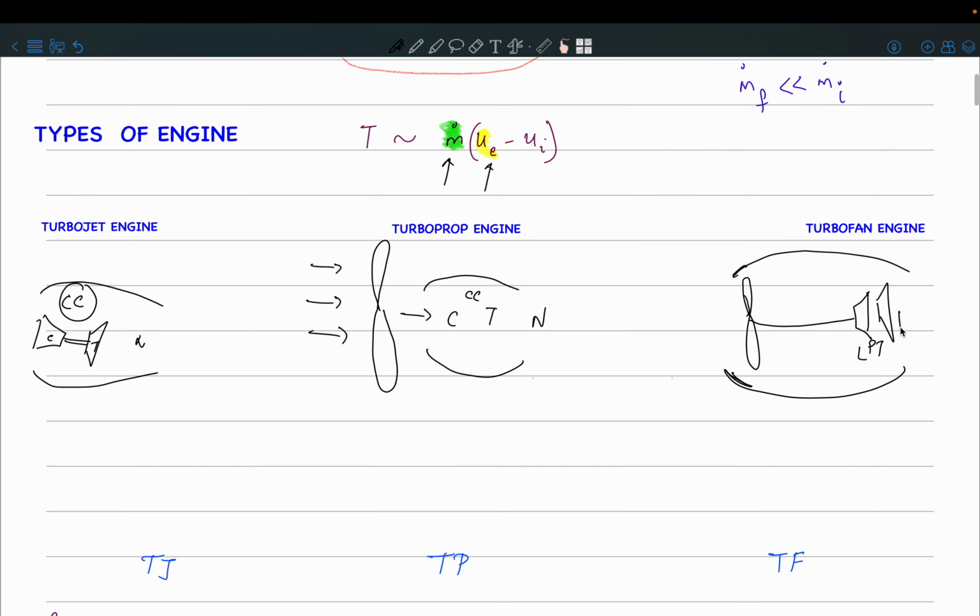That high pressure turbine is going to run the compressor, and there is a combustion chamber. Okay, so this is a multi-spool arrangement, and if you're taking in some m dot here, there will be a cold flow which is m dot c, and there will be some hot flow which goes through the compressor. It undergoes combustion along with the fuel, and then it runs the turbine. So that is m dot h, and the bypass ratio is defined as m dot c by m dot h.